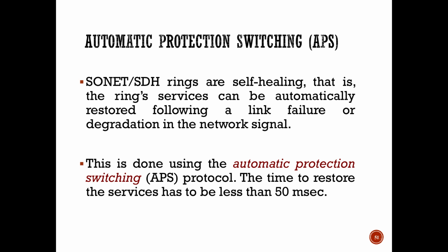SONET/SDH rings are self-healing, that is, the ring's services can be automatically restored following a link failure or degradation in the network signal. This is done using the automatic protection switching, APS protocol. The time to restore the services has to be less than 50 milliseconds.